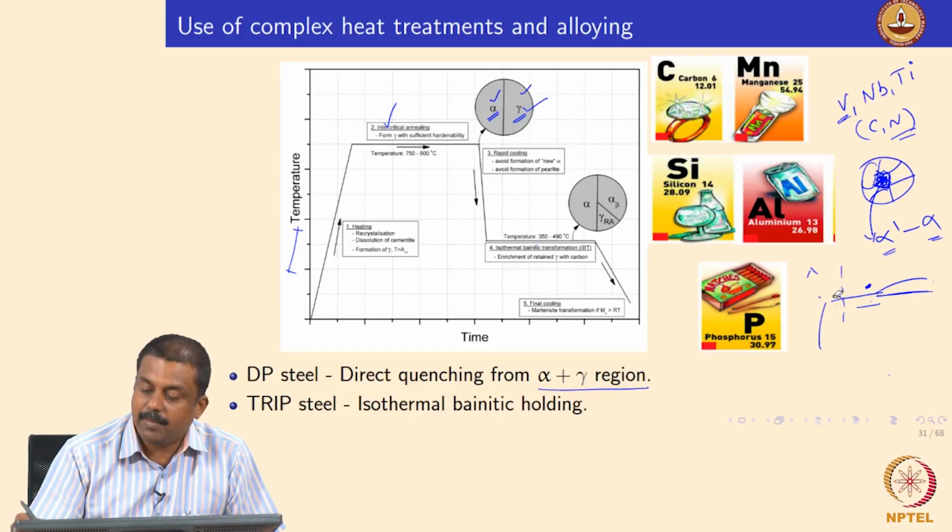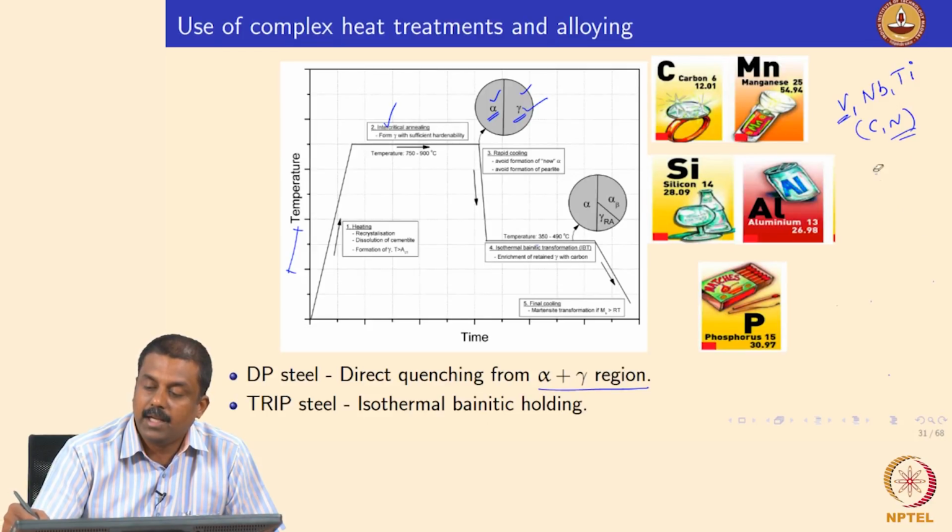So, what is bainite again? Bainite is a mixture of ferrite and cementite in a different morphology than pearlite, right. We can have either upper bainite or lower bainite. In upper bainite, the ferrite lath forms and the carbon subsequently migrates to the adjoining regions of this ferrite lath, and then you end up forming cementite at the interlath between, for example, the ferrite laths. So, we will have ferrite and this is cementite. The upper bainite microstructure typically is like this.